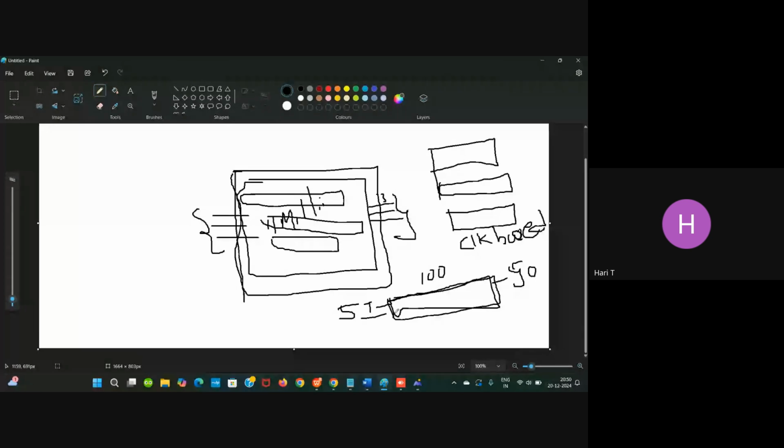See, for example, there are 100 scan chains and one single scan in and one single scan out. There will be more tester cycles and more test data volume in terms of pattern. The more test data volume and the more number of patterns tends to more ATE test time when implementing EDT with one scan in and one scan out.